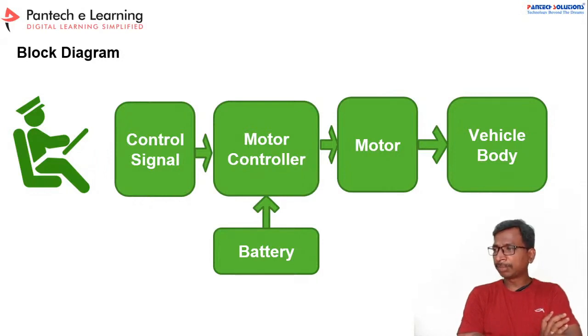Interior permanent magnet synchronous motor. Yes, BLDC, I mean BLDC and then DC motor are the two for two-wheeler as well as three-wheeler applications. Whereas for high power applications, we have to go for the induction motor or PMSM motor or SRM motor, right?